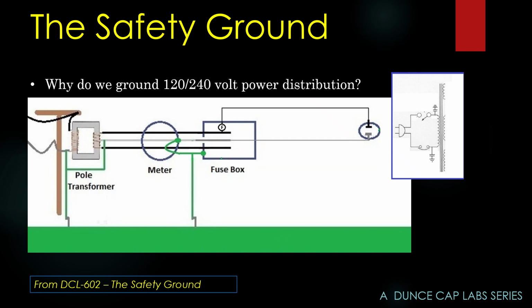One of the things they did to try to get around this is they invented the polarized outlet. Now one blade is wider, so this is tied to ground. Except if you don't ground the cabinet, which Heathkit did not do in this case, and this still touches the cabinet, this is still a hot cabinet, and if I touch it, I get electrocuted. So this kind of worked. I mean, it kind of helped. If they would have tied this to ground, we would have been okay.